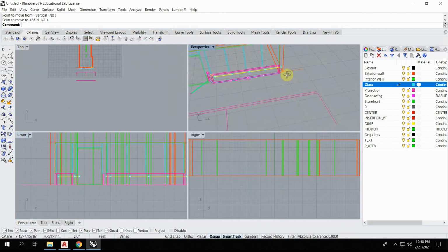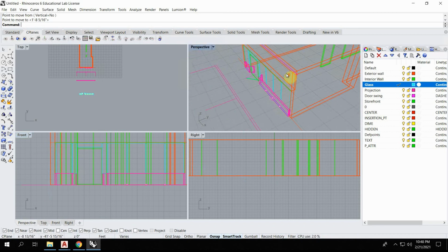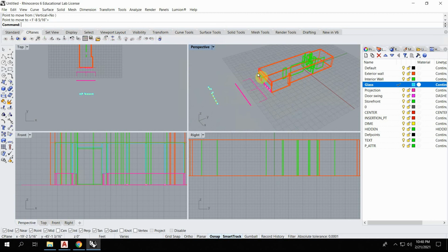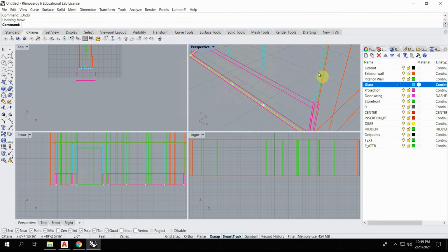But if I look, that actually worked pretty good. So let's say I move them and I think I'm going straight up and I do that. But in reality, they've moved all the way over here because it clicked to something else. So it's very often in Rhino that students have issues with trying to move things straight up and down.